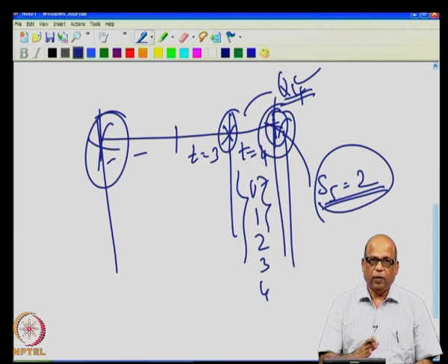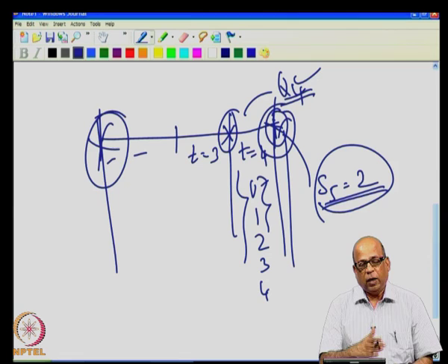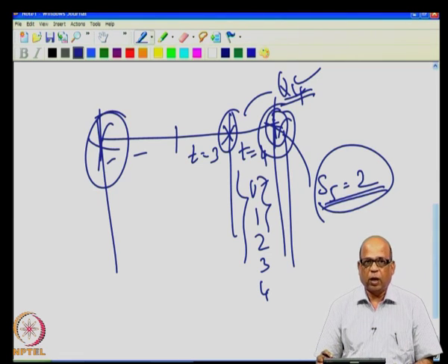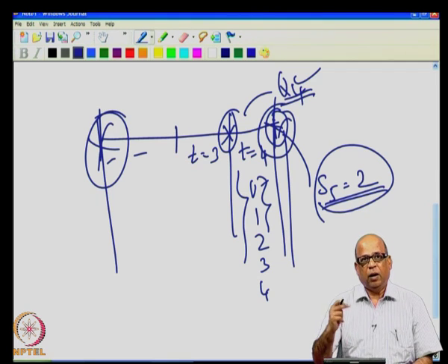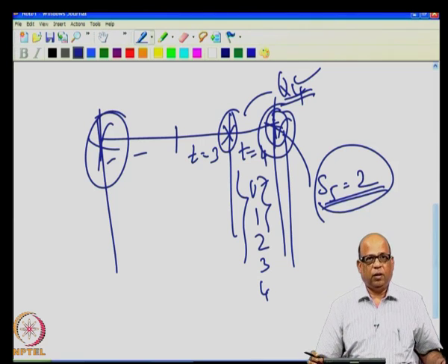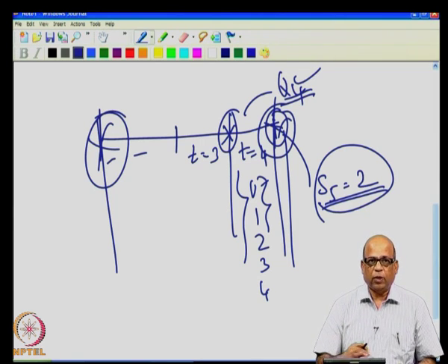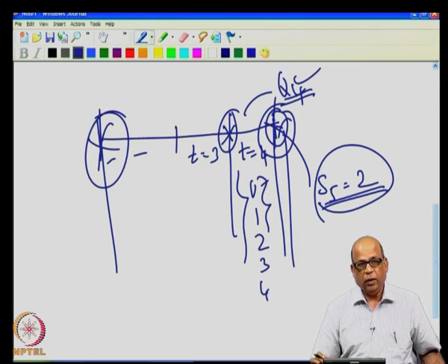So, in any given table, you should always look at whether you are meeting all the conditions or not. In fact, we did this in our calculations, because every time we were checking whether the resulting storage is in fact below the capacity of the reservoir or not. That is how we pick the R combinations, that is the release combinations along with the given S values. So, there are several subtleties you should start applying, and then you will realize, keep all these subtle points in mind in reservoir operation.